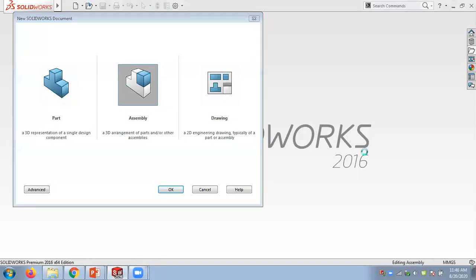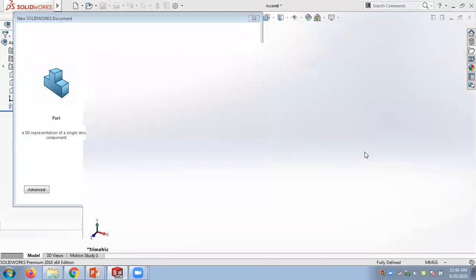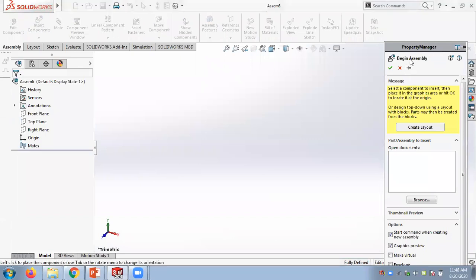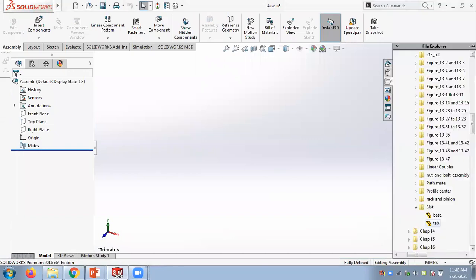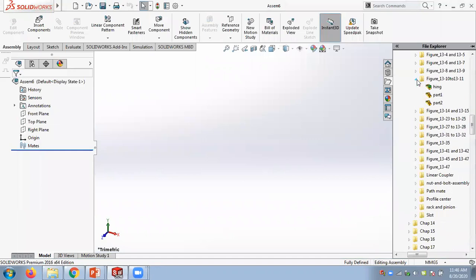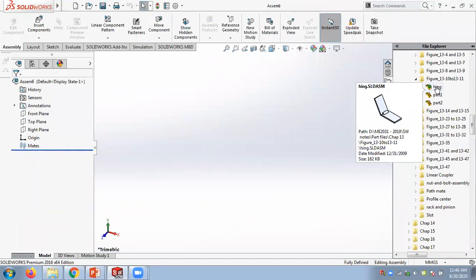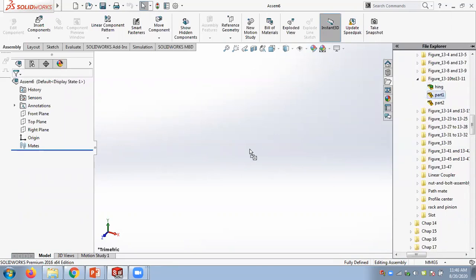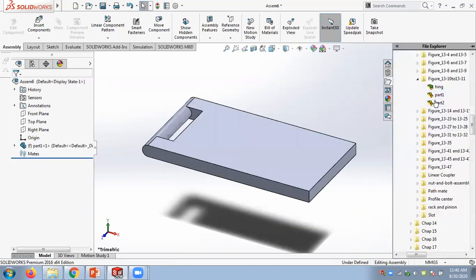Actually, this hinge mate can be obtained from normal mates. Some of the things I am discussing here can be obtained from normal mates, but you have to do several mates. That's why they have introduced the direct tool. So if you look at the hinge here, we can get this mechanism by normal mates. But we have to do at least three operations. To reduce our time, we can use inbuilt features like hinge tools.